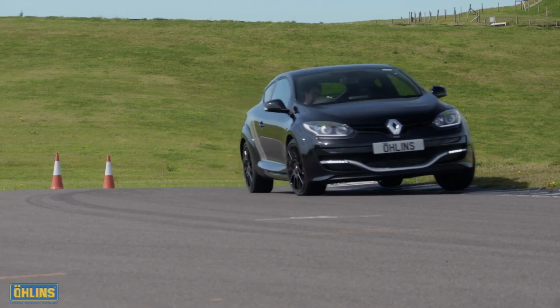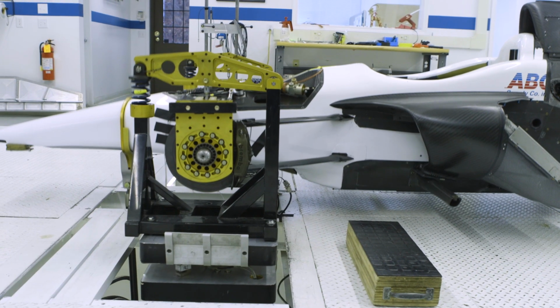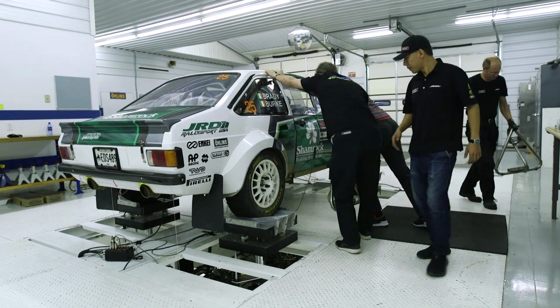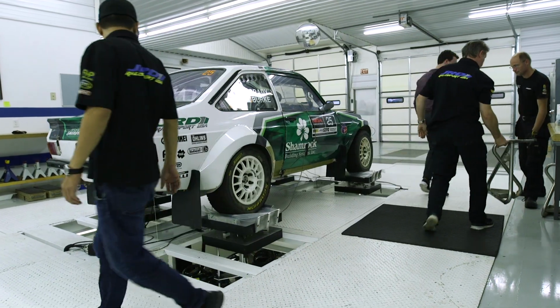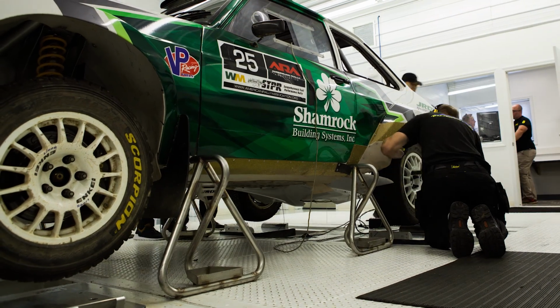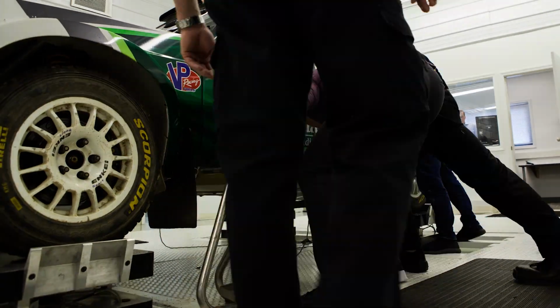As a bonus, we also do not put any miles on the engine, the gearbox, and tires, and we do not use any fuel. The risk of damaging the vehicle due to an off-track excursion is also eliminated. So a lot of our customers find that testing on the shake rig is a lot more economical for tuning the suspension than track testing.